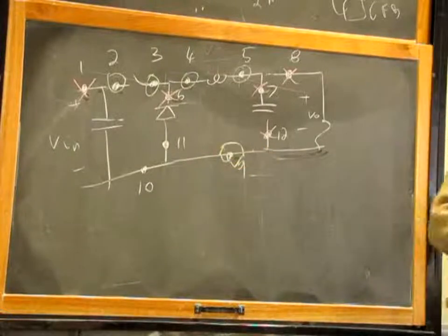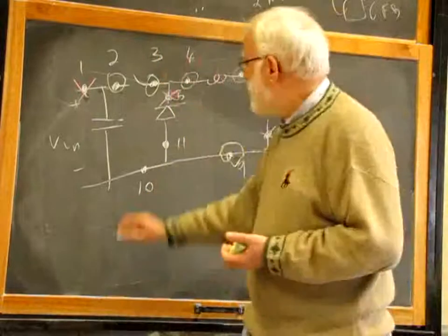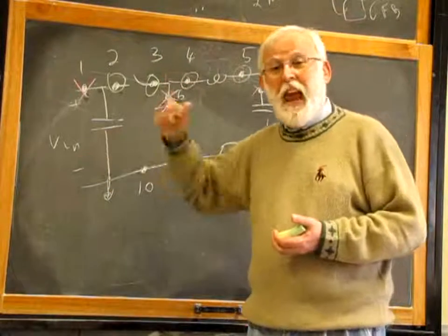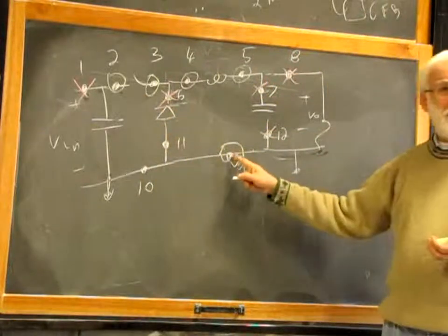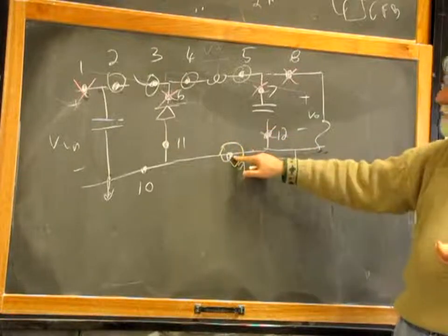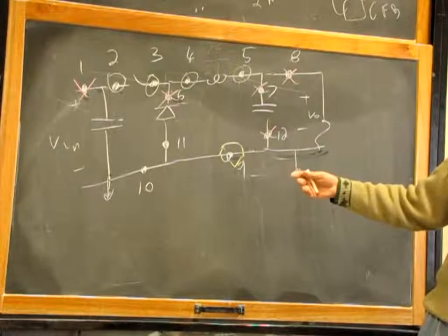It could be, but remember that you have doubts, because if you connect it to the ground, no, because it's the negative of the relay, and you connect to the ground this node, you are basically shorting this current section. So the current that flows back flows partially through here and partially through the ground connection, and so you would not measure all the current.